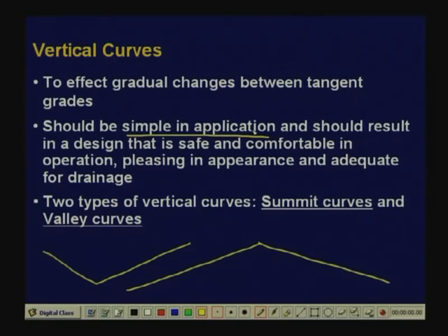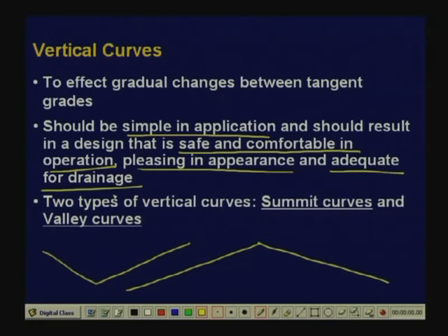Number 1, it should result in a design that is safe and comfortable in operation, pleasing in appearance and adequate for drainage. All these considerations we have to keep in mind when we are going for the design of vertical curves. The design should be safe and comfortable in terms of operation, pleasing in appearance and adequate for drainage. All these considerations are important.